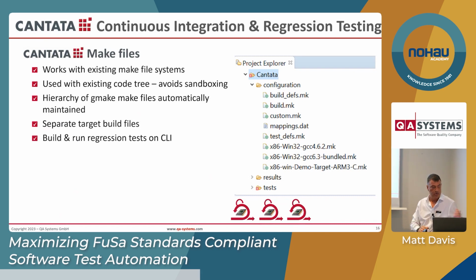So outside stimulus, like if there's a UART in play, that becomes a little bit difficult in the process. Yes, it does, and that's why a lot of people will run tests on a target platform, depending on the nature of the device. Where you run your test is often dictated by the safety integrity level. If you are doing an ASIL D system, or the highest level of integrity, say for a Class C device in medical, you are expected to run your test on the physical hardware.